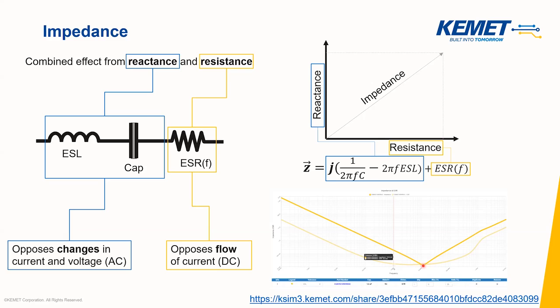Our next question says, what sort of performance trade-offs should we be considering as we move to capacitors with higher capacitance, higher permittivity? Yeah, that's a good question. There's always a trade-off, and many times I tell people that engineering is just the careful balancing of these trade-offs with your design requirements. This is a bit of a rule of thumb, and it changes somewhat across different capacitor technologies, but generally, the more voltage you have, the less capacitance you have.